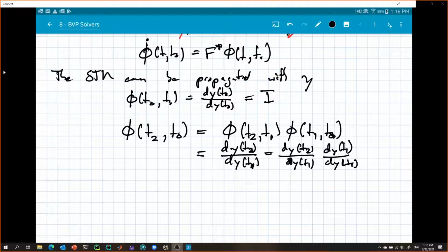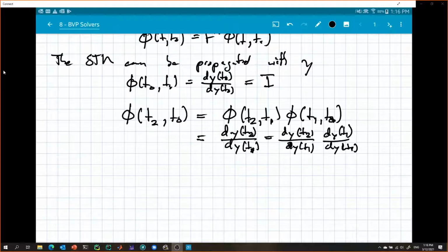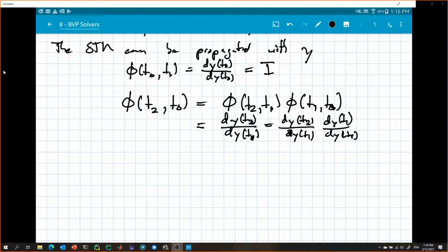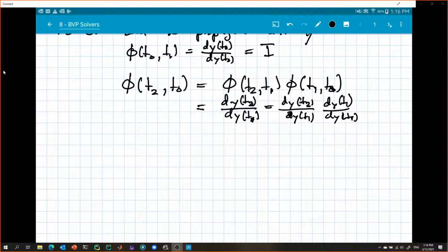And then there's an interesting paper you could look up from a colleague that used to be here at Purdue. It was his master's work. He derived a fast shooting method that basically calculated the state transition matrices for each time step on a GPU, and then you could quickly combine them all together just by multiplication. So this actually has uses too.